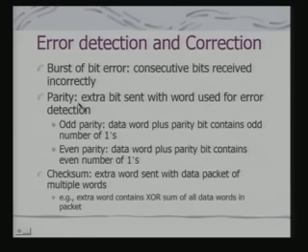The most common mechanism is parity. An extra bit is sent with the word, used for error detection. If there is an isolated error, we can detect it. If there is always an even number of errors, it gets masked, and I cannot detect that error if I am using parity. It can be an odd parity or an even parity which is used. In fact, this is a basic error detection scheme which is part of any of these asynchronous protocols, even as simple as the RS-232C protocol.